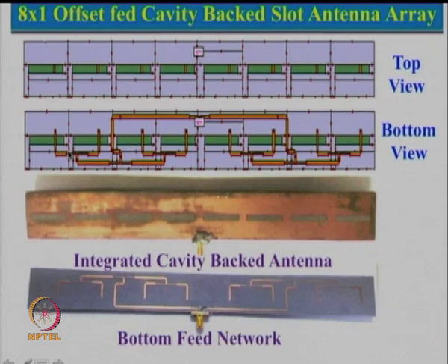So the impedance at this point will be Z0 square divided by the load impedance. Now Z0 square is 70.7 square, which is actually 50 into square root 2 whole square, divided by 50, that gives us 100 ohm.